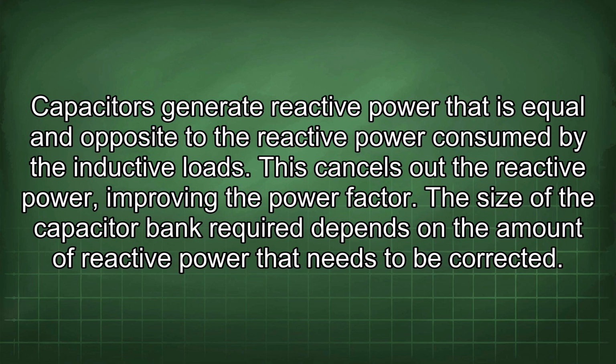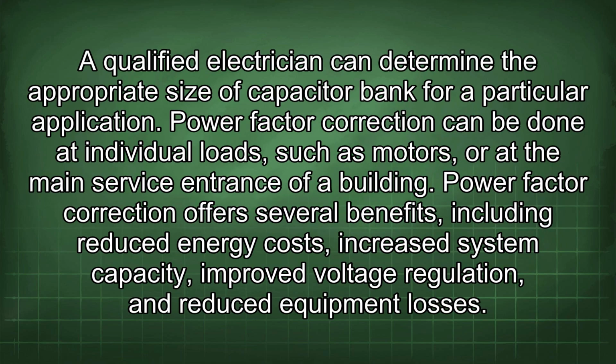The size of the capacitor bank required depends on the amount of reactive power that needs to be corrected. A qualified electrician can determine the appropriate size of capacitor bank for a particular application. Power factor correction can be done at individual loads, such as motors, or at the main service entrance of a building. Power factor correction offers several benefits, including reduced energy costs, increased system capacity, improved voltage regulation, and reduced equipment